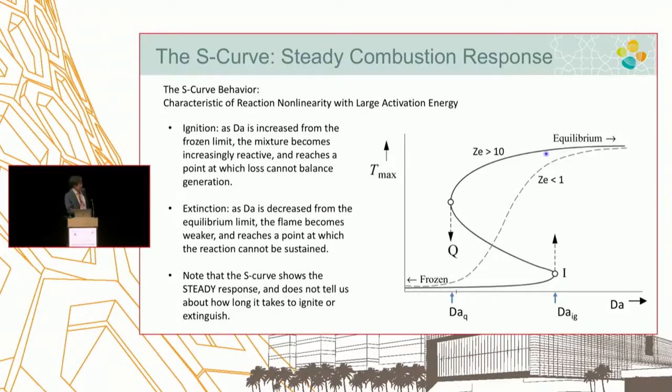I have an input parameter. The Damkohler number, like I said, is an important system parameter. It determines, within my reaction system, in my burner, or within the flame, the ratio between two characteristic time scales. For each of those, you can find the actual steady solution for the flame temperature you can get.